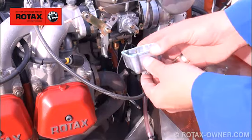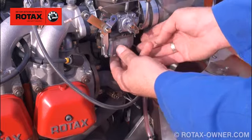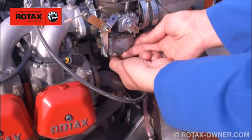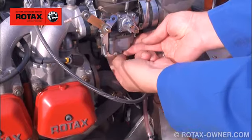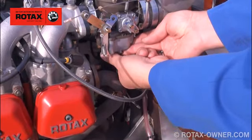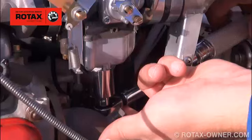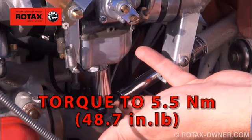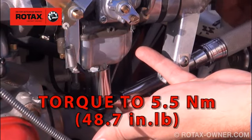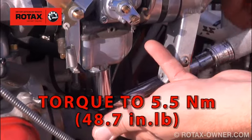On a Type 912, you would close the spring clip. On this 914, we will install with the attachment screw and its new O-ring. Tightening torque of 914 attachment screw is 5.5 Newton meters or 48.7 inch-pounds.